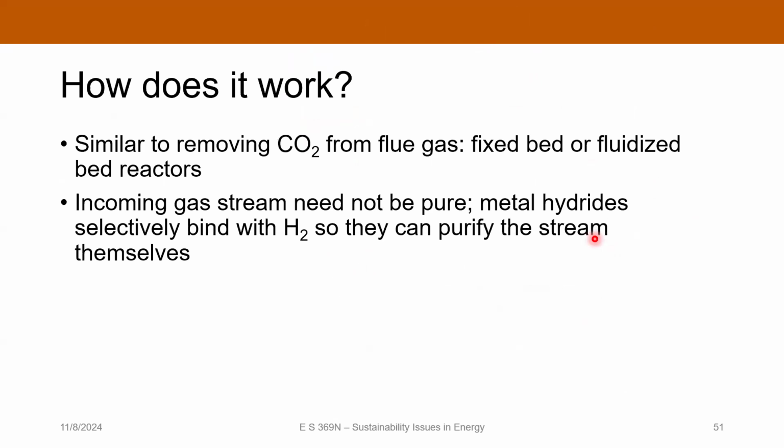Okay, so you would charge these things in something similar to what we use to remove CO2 from gas. And the nice thing about this is that you don't need to purify the hydrogen before you run it through these. Because they exhibit selective binding, they'll pull the hydrogen out of whatever gas stream is coming in. They won't pull anything else out.